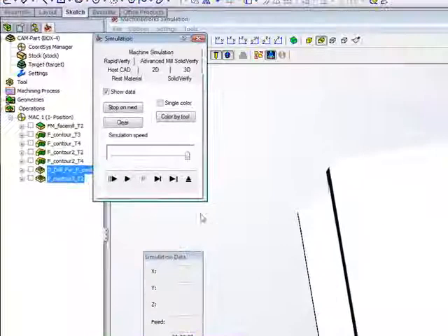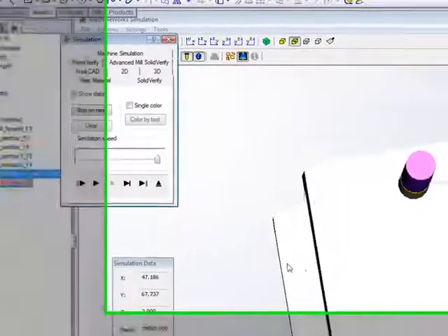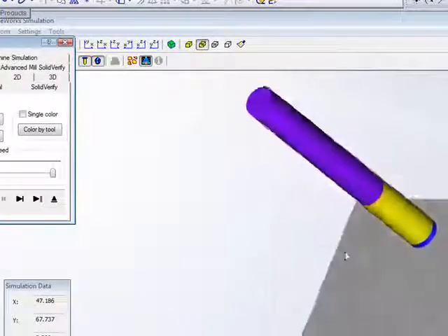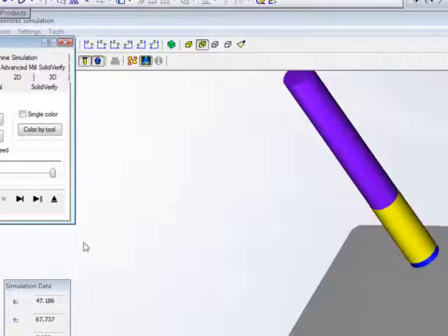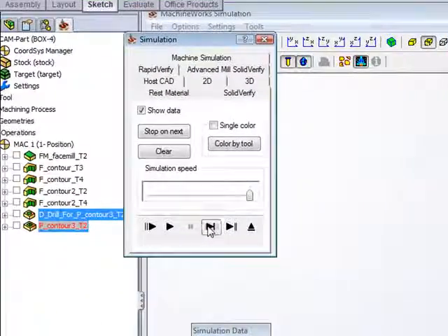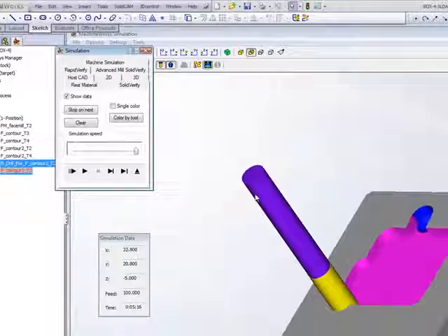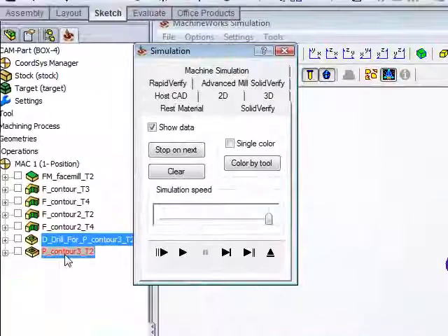You'll see that my drilling point is now at the new spot, and then my end mill for the pocket will go in exactly into that spot as well. So in other words, the drill point is always attached to that point for the pocket, even if I change it, and I do not have to go back into my drilling operation to create that drill point again.